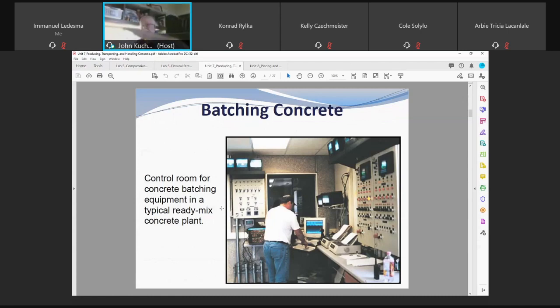As the scale is starting to tip. It's a beam scale. I don't even think they were digital back then, or even dial. A lot of them had those beams. But now everything's on the computer. He's got a mix design, he's got a code, the computer feeds it, controls the gate openings, controls the pump for water, controls the admixtures, and so forth. So this would be a typical operation that you would see.